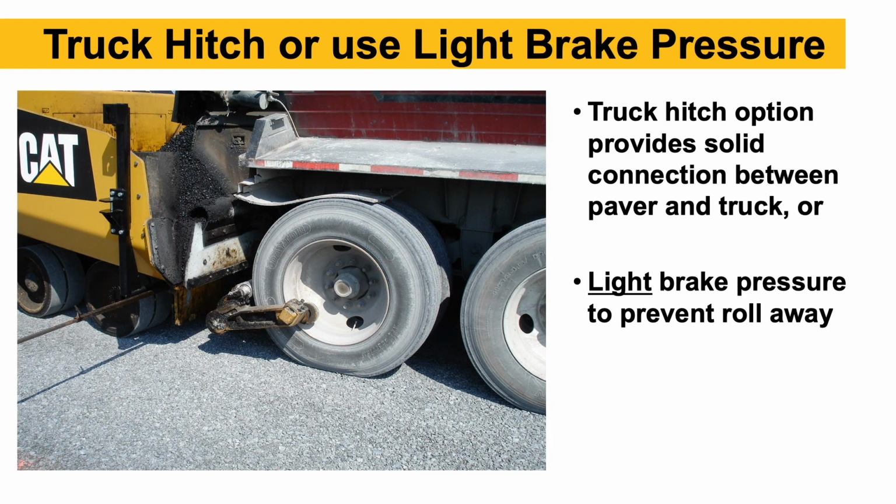Some pavers have truck hitches on them. So in this picture you can see the hitch. Those are out wide once the paver picks up the truck and those push rollers touch the rear tires on the truck. The hitch is hydraulic, extendable in and out. It'll come in and kind of lock in on those truck rims.